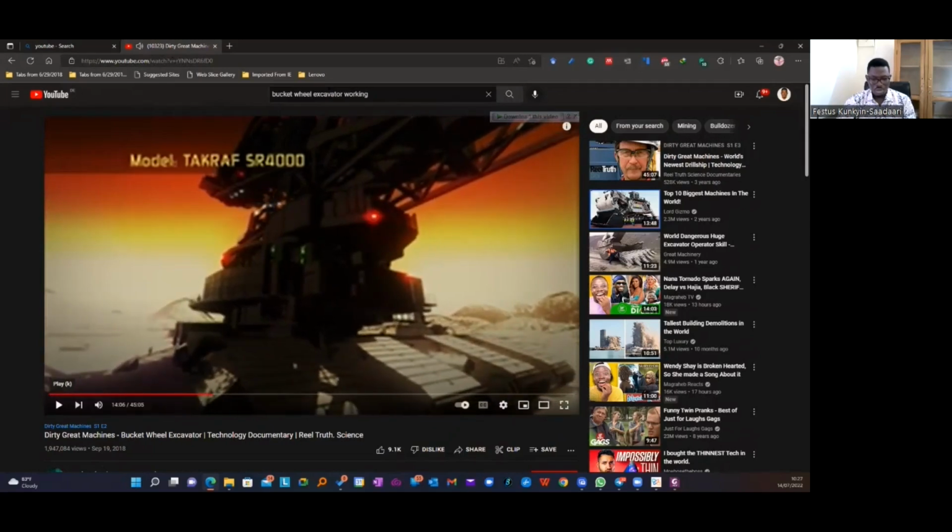Most of these soft material machines we use are named after how they scoop or fetch the material. So this one is called the bucket wheel excavator. It is kind of like a wheel, but instead of the wheel revolving, it has fixed buckets with teeth along it. As it whirls around, it scoops the material, and when it goes up the boom, it dumps the material before it moves back again and fetches more. So that is how this type of machine operates.